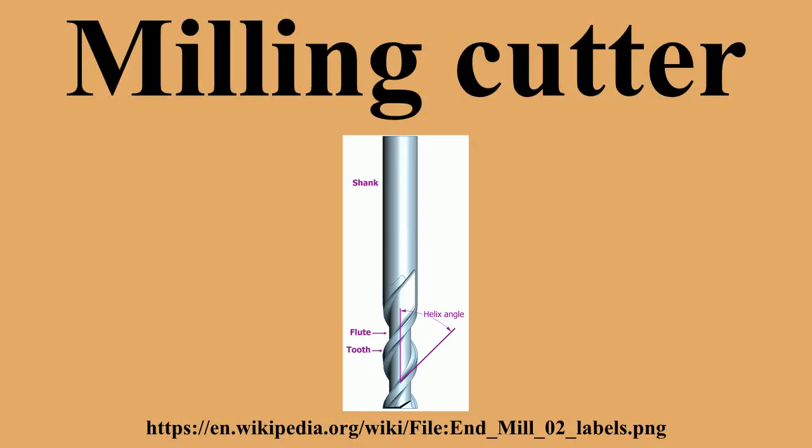Rapid stock removal with heavy milling cuts is sometimes called hogging. Roughing end mills are also sometimes known as ribbing cutters. Ball nose cutter. Ball nose cutters or ball end mills are similar to slot drills, but the end of the cutters are hemispherical. They are ideal for machining three-dimensional contoured shapes in machining centers, for example in molds and dies.